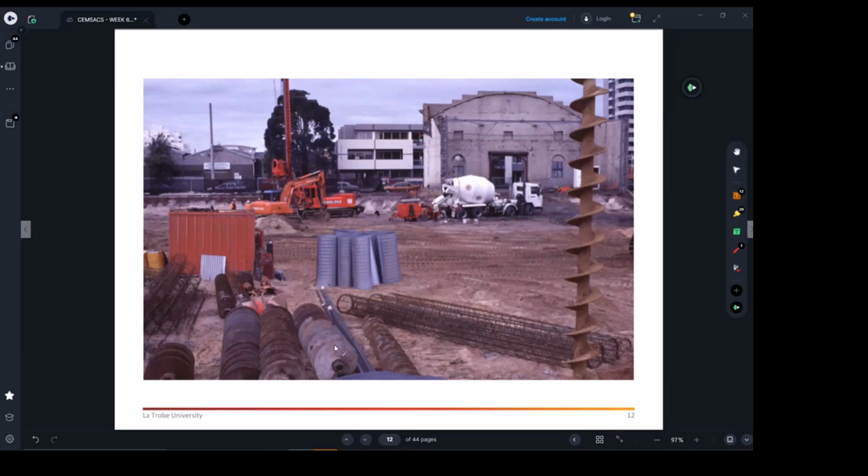At that corner, you have the different augers you may connect as long as you want. The soil report will guide you, say maybe 9 meters, 12 meters deep, for bored piers with the CFA method. If they need more, they can attach more and go deeper into the ground. Once they reach the design level, they start lifting up.